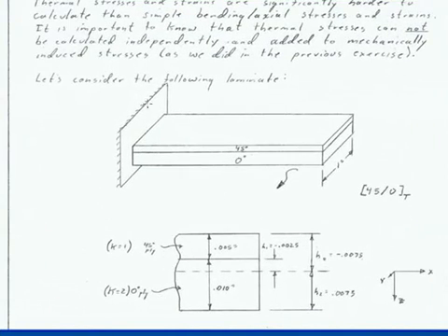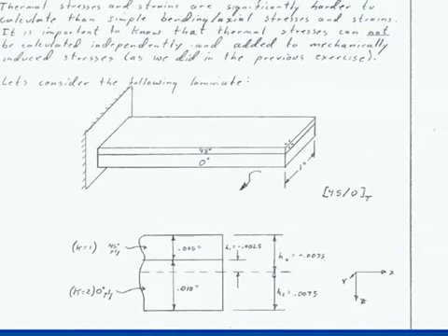depiction of the laminate that we're going to build. The top ply is a 45-degree ply. It is 5/1000ths of an inch thick, as you can see here. The second ply is 10/1000 thick, and it is a 0-degree ply.